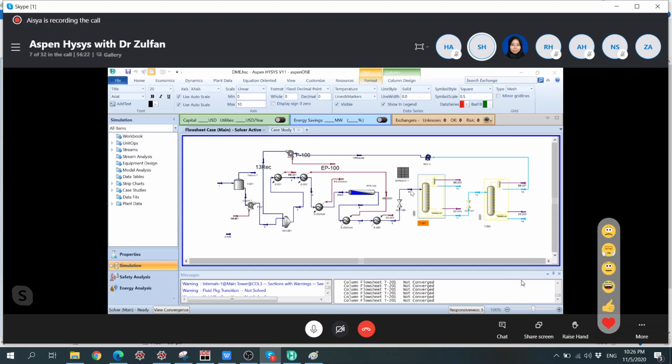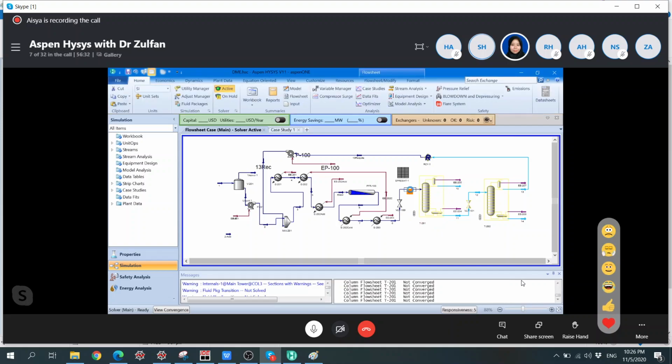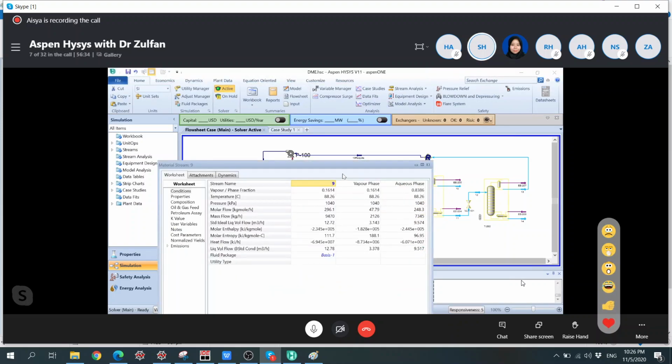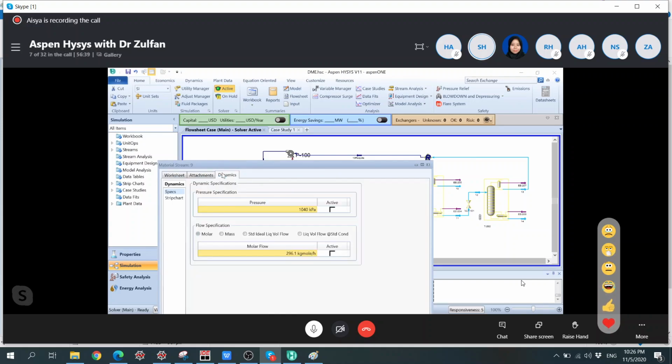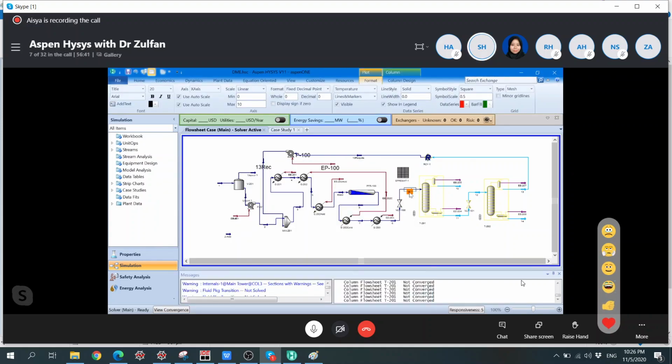Right, that was the complaint by HYSYS. It says that stream number 9 doesn't have enough data, but in fact it has all the data. So at least to follow HYSYS recommendations, we will just use this. We will relocate that recycle unit to stream number 9, so that you have stream number 9 as the input value.